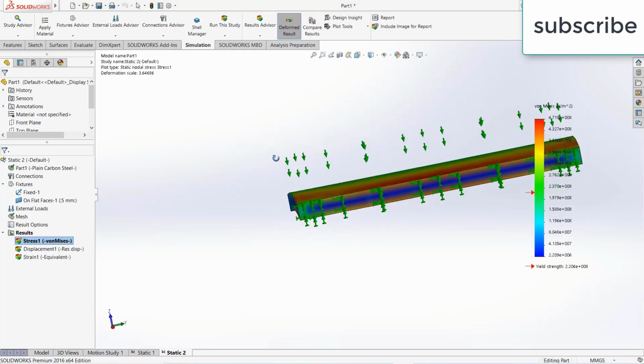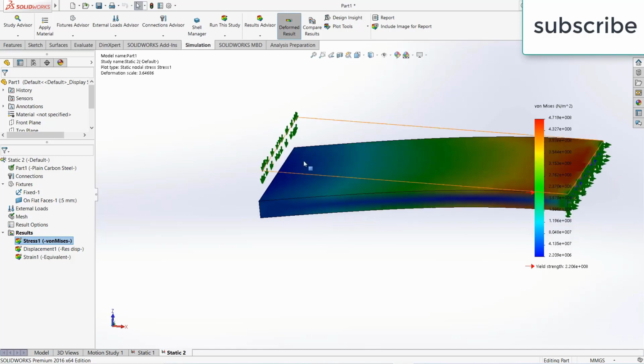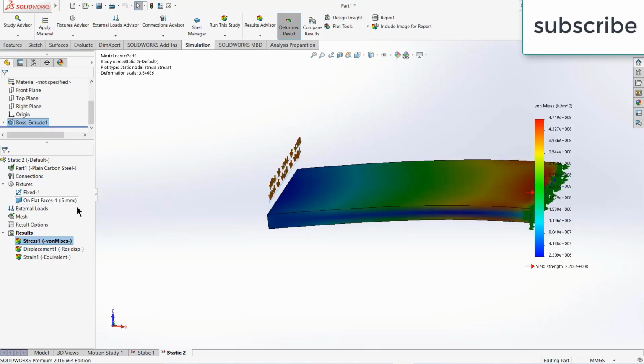Here you see I got a simulation result, and if you notice correctly, I didn't apply any kind of load. What I have done is I simply told SolidWorks to move this edge by 5 mm, and you can see for a particular distance it tells me how much stress is generated here. As you can see, the value is quite large, 4.71 times 10 to the power 8. Okay, now let's see another option.